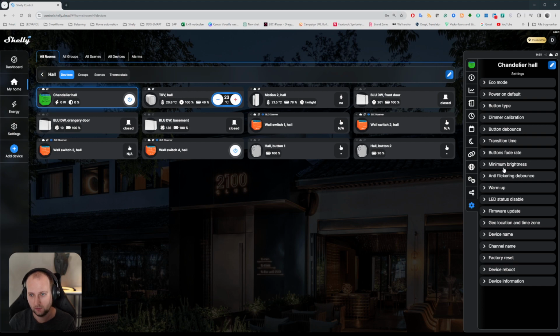Shelly works with your wall switches. So you are simply connecting your wall switches to the input of the devices. And then you can turn on and off your smart lighting from your wall switches, but also from the app. You will never just cut the power to the wall switches. It just works like always. And if the internet goes down, it works like a normal relay. So I call it a smart installation stupid, because it works stupid like you always used to, but you have all of the smart features from the app, and it will always just work when you make it hardwired like this.